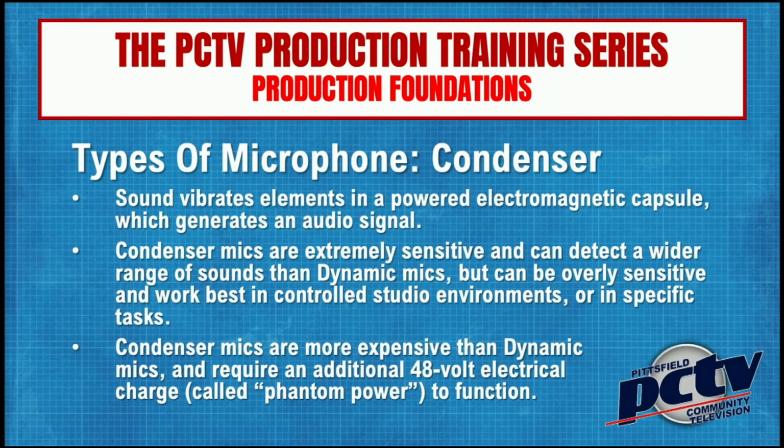Cameras and soundboards are capable, when they are told to, using a switch on the board, of sending that electrical phantom power signal to power up the microphone. So if at any point in time you have a condenser microphone in the field, you've got it plugged in, you know the microphone is working, it worked yesterday, and you try to use it and you can't hear a darn thing, what's very likely is that the microphone is not turned on. So you want to make sure that you're powering the microphone for it to work.